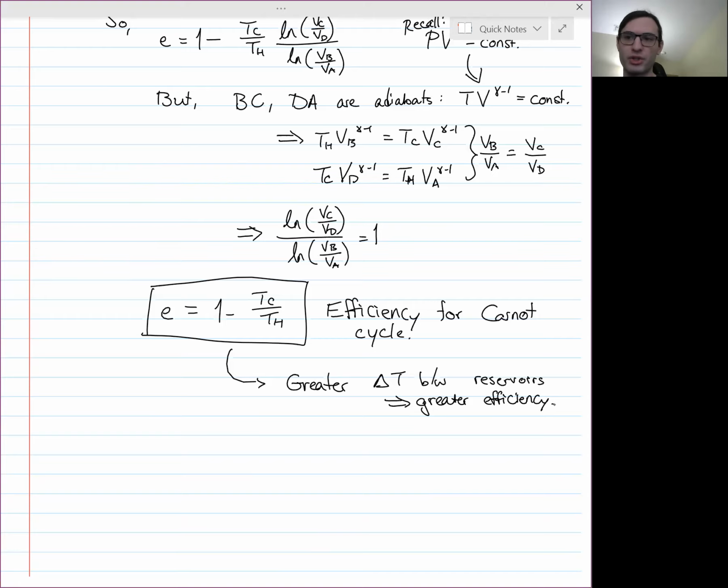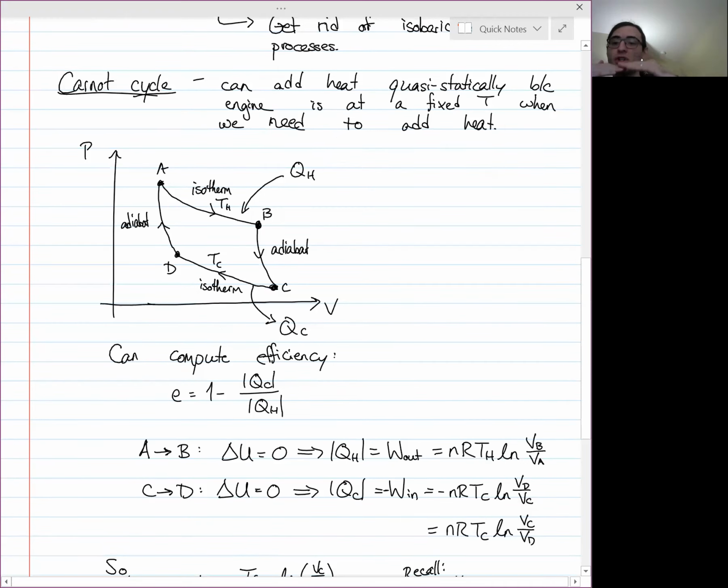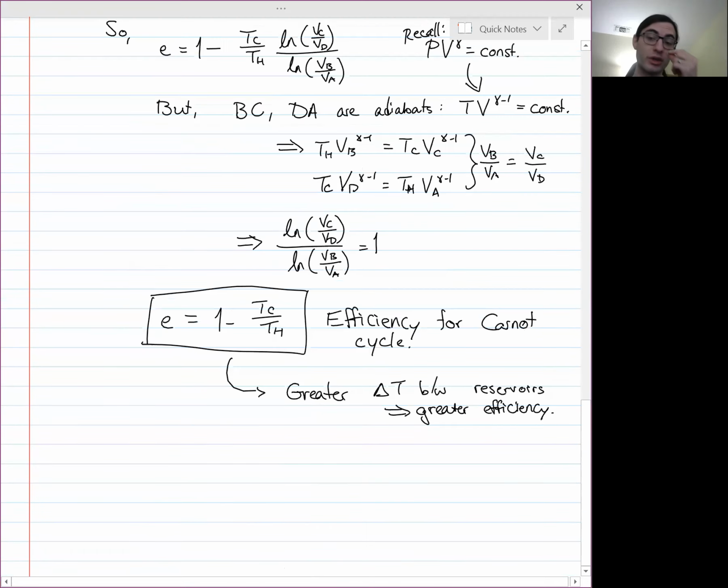The Carnot cycle is a particularly nice cycle. It's not used in general in a whole lot of industrial environments or in automobiles because it's slow. Because it involves isotherms and very small temperature differences between the environment and the isotherm itself, the heat transfer during that part of the process is very, very slow. And so it's just not particularly useful. But if you have enough time in the world, you can convert thermal energy to work at maximum efficiency.